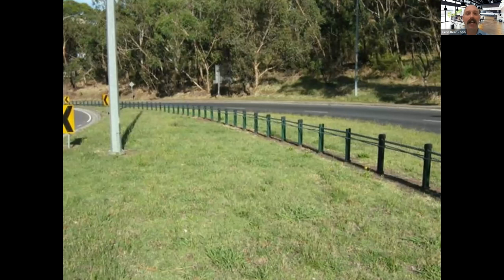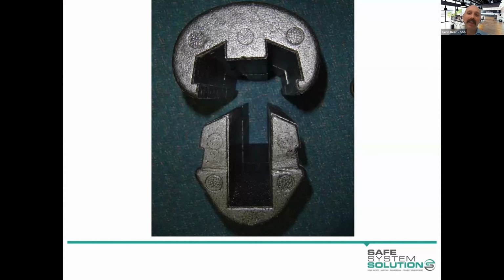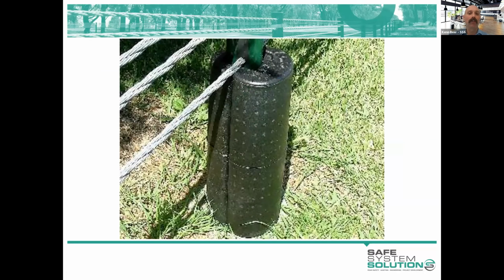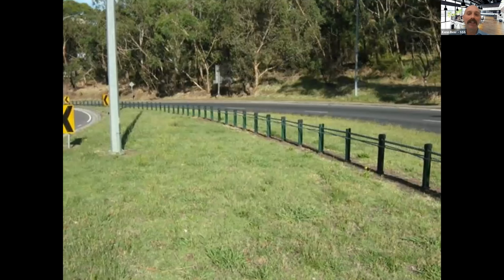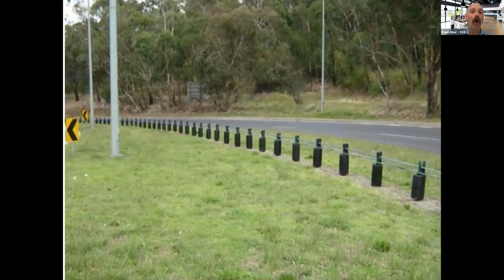We do have a device that is used around the country, not approved for use in New South Wales at the moment. Maybe, well, there's a suite of products, but they're post cushions. So they're basically football goalpost padding, the equivalent of that for the motorcyclist that's going to hit it. So, of course, that is not going to be as effective a redirecting device where you would run along the system. This is trying to absorb energy over a very short distance, it's padding. Never been tested under the European test protocol, and I suspect that's because the suppliers know that it's not going to pass.